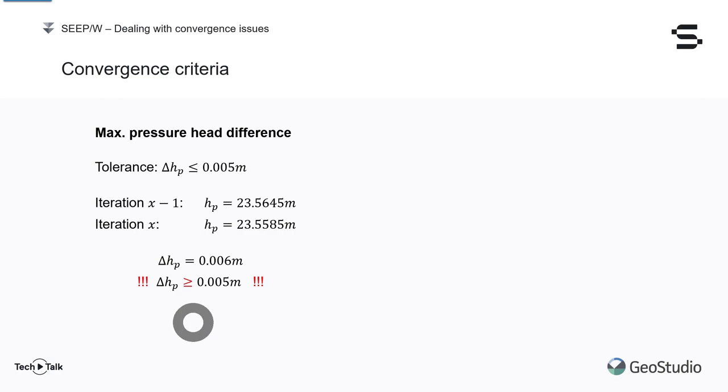results view. For any node where the maximum pressure head difference criterion fails, the solver will check a second convergence criterion to verify if the convergence issue is very important: the significant digits equal criterion. While the first criterion checks for numerical stability for small pressure differences, the second criterion investigates if the answer remains the same from one iteration to the other when larger pressure differences are involved.